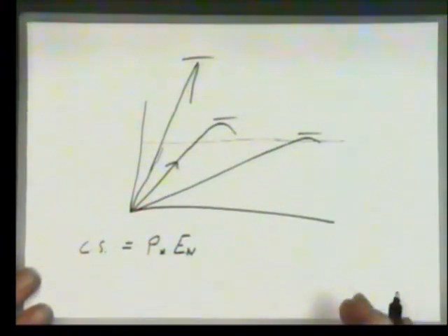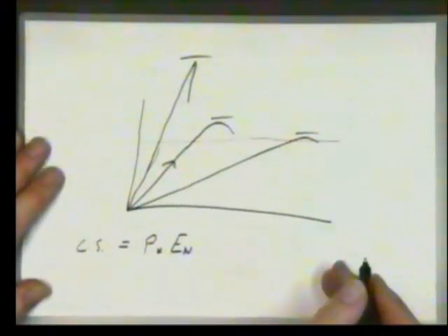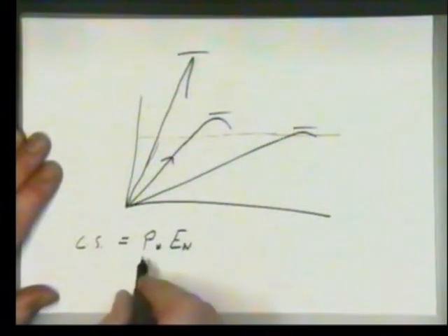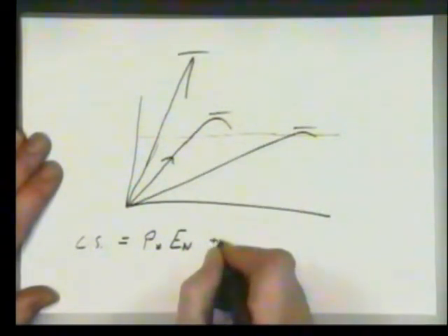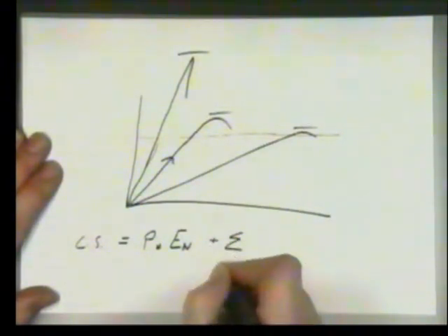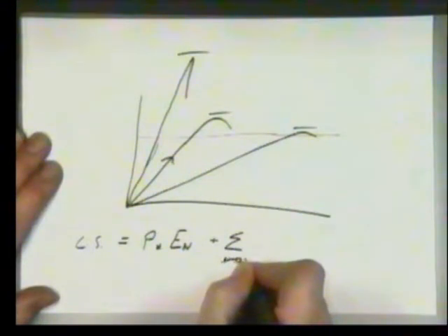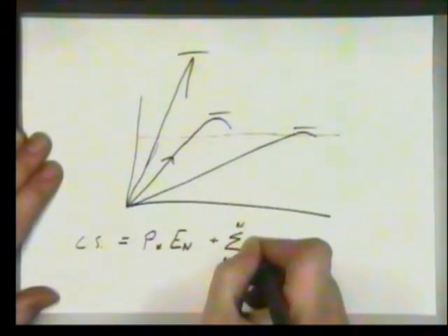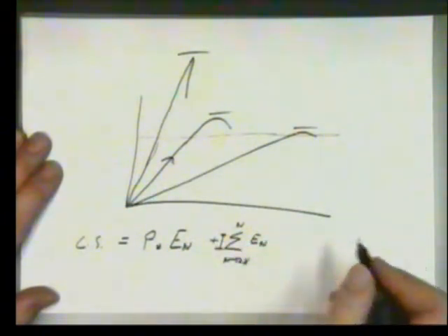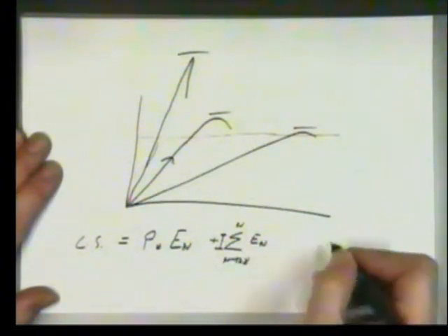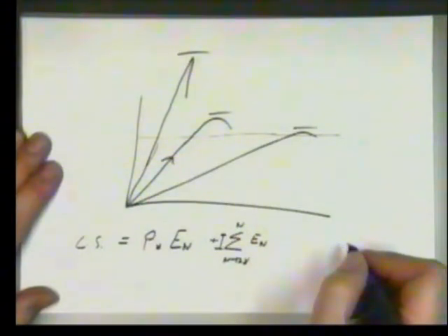another algorithm. I'm going to use the sample data version now. I'd say control signal equals proportional times the instantaneous error now plus sigma, the last 128 samples. So there is our I term. But the other thing I'm going to do is calculate the rate of change.